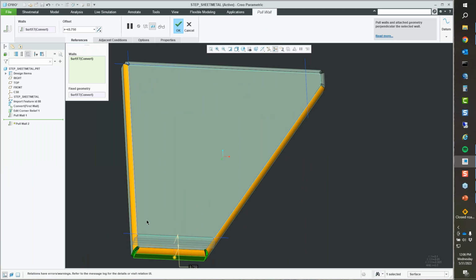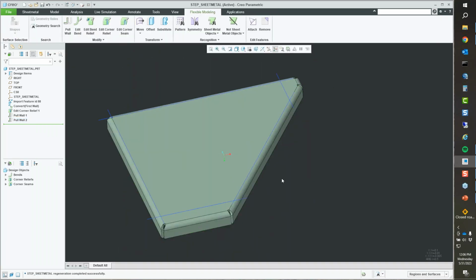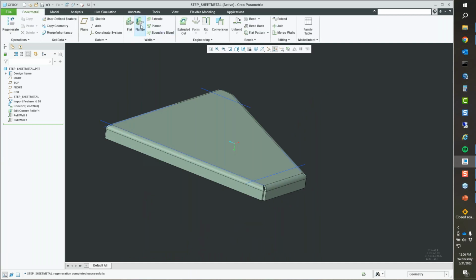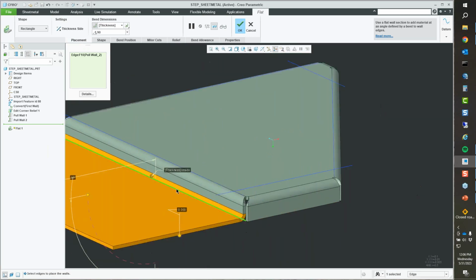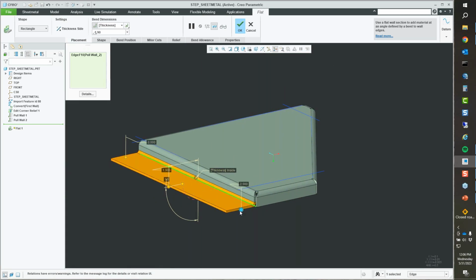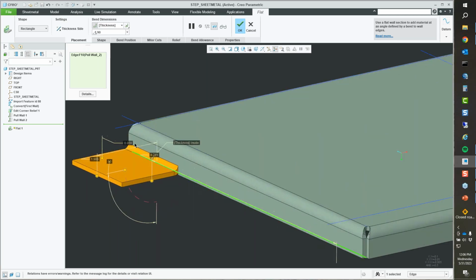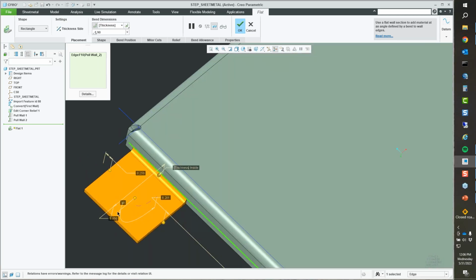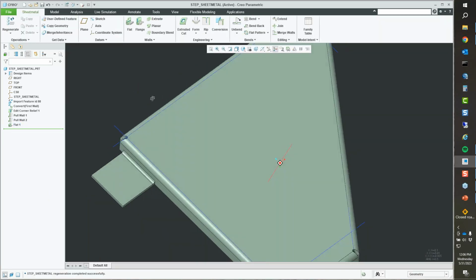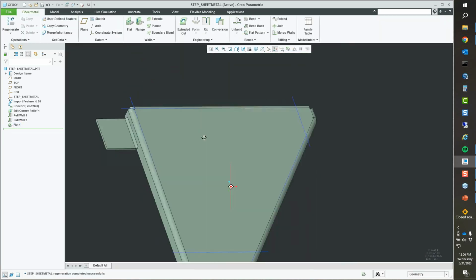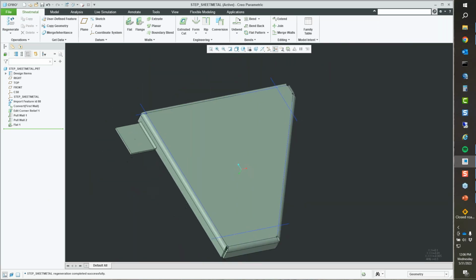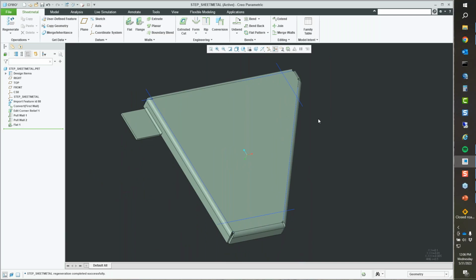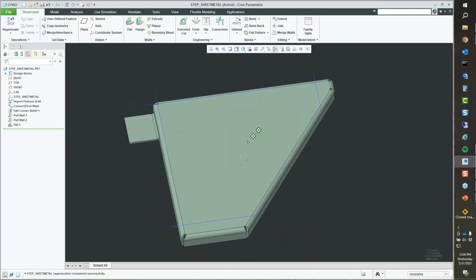And it'll take the side seams with it. So I can change some of the length of that. I can change some of the height. And of course, it's still in sheet metal, so maybe I need to add a flat wall to it. Grab the other edge. And maybe a little tiny offset wall to it. And again, remembering that this was an imported part that I'm working with, right? That's kind of the whole idea of that thought, is that when you bring an imported part in, if it's a constant thickness part, you can convert it into sheet metal and do some of those sheet metal tools with it, which is pretty outstanding, I think.